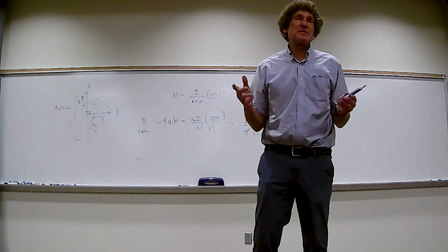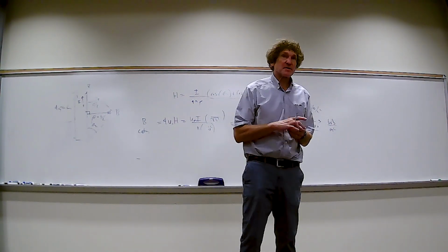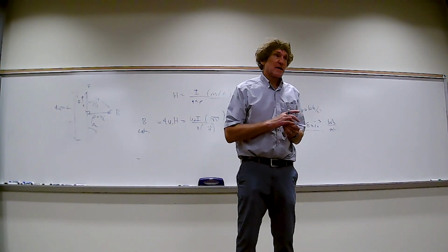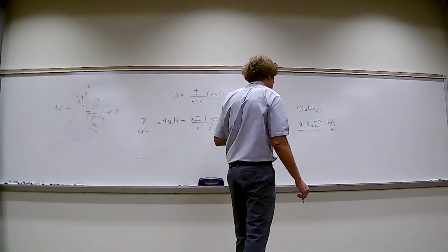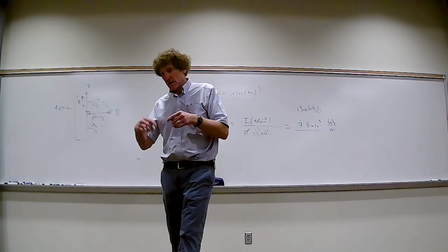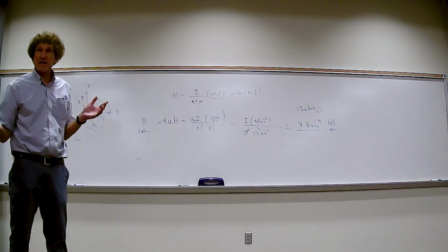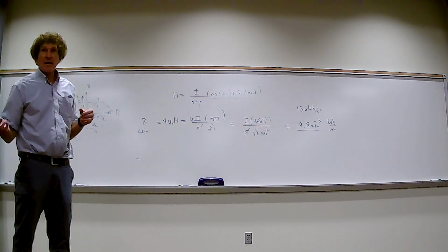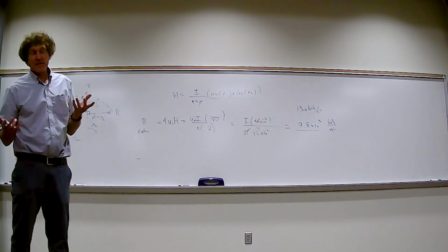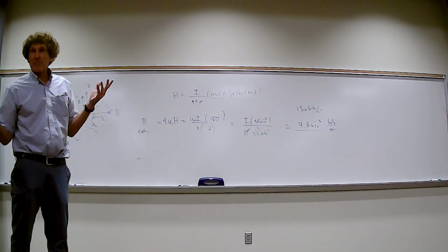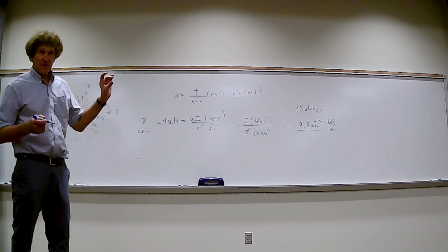Anything else? By the way, these problems, most of the time, really boil down to your understanding of the induced voltage and direction of induced voltage. It's always the time rate change of the total flux through a loop, but you have to put a negative sign to get the sense of the voltage.